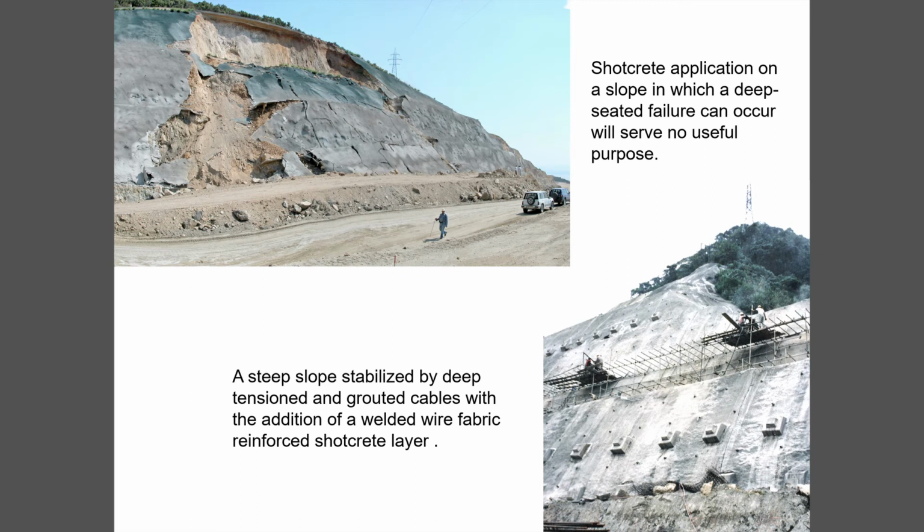In the early days on the Egnatia highway in Greece, a highway that runs 680 kilometers across northern Greece, they applied shotcrete to many slopes, and they subsequently went back and took it off because they found it was unsightly on the one hand, and B, it wasn't very effective. What they did was develop a series of meshing solutions, and even little plant boxes which were held up along the slope and grew plants and stabilizing material of that sort. So shotcrete was actually taken out of operation there.